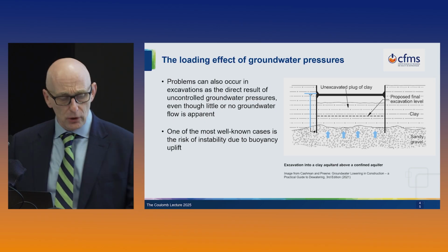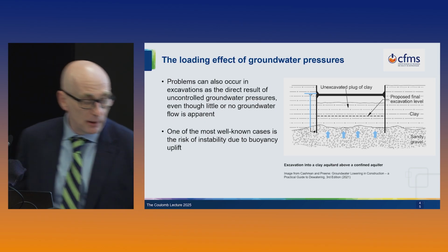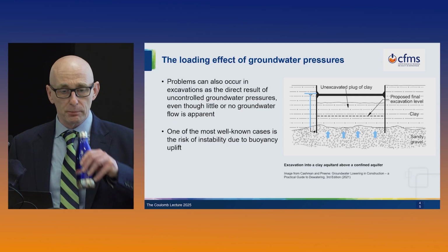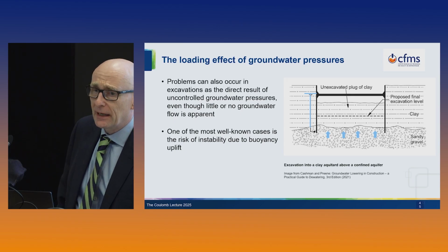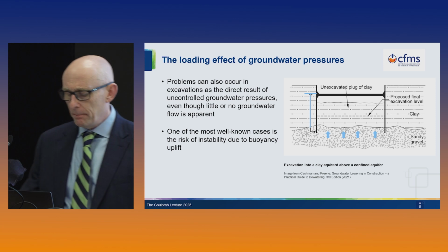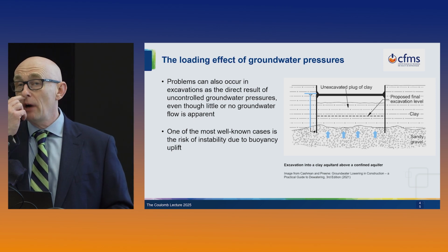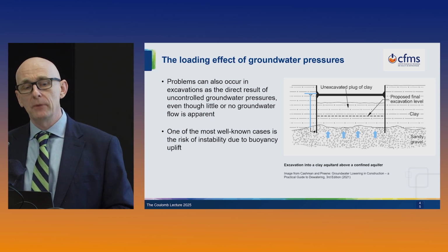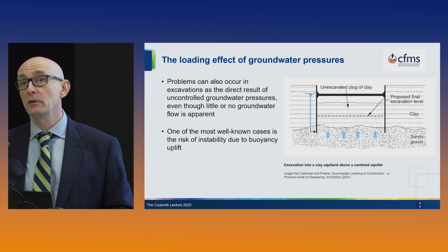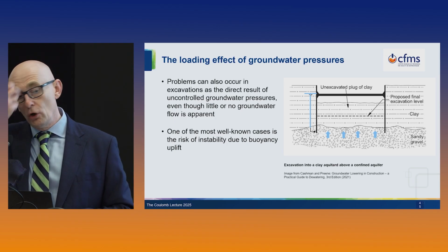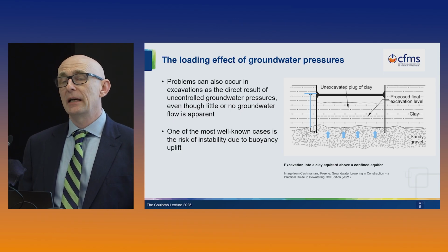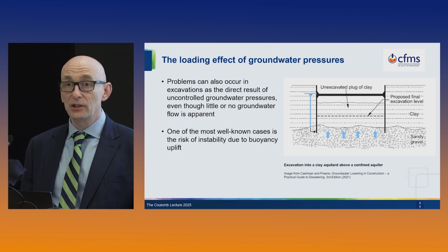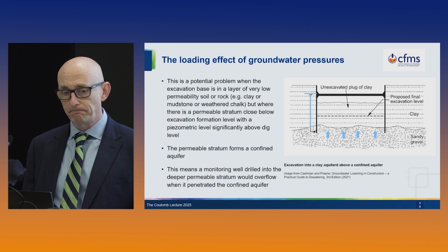And I want to talk about the third part of the theory, which is the loading effect of groundwater pressures. Because so far I've mainly been talking about situations where we have groundwater flow, and groundwater flow is part of the problem. But you can get groundwater problems where there's no apparent or no significant groundwater flow, and that normally results from uncontrolled groundwater pressures. And one of the classic cases is buoyancy uplift or hydraulic uplift.